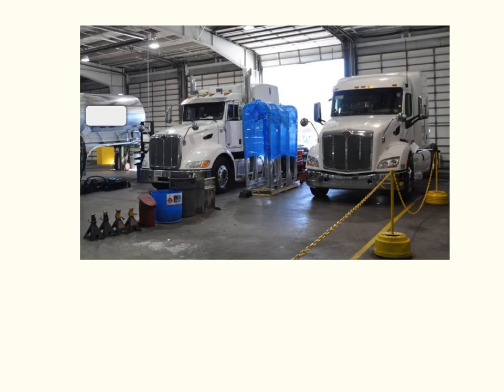The last area we're going to look at is where we have to service the tanker trucks and the tanks themselves. This one's quite simple, really. We have a Zone 2 location upwards of 450 millimeters off the floor in the entire shop. Now, if you have offices attached, usually what will happen is, in order to avoid having to consider the offices as a class location, you'll run a curb before you frame the walls, and that curb will be up 450 millimeters, which suitably cuts off the offices from the shop portion, which allows us to wire in an ordinary location.